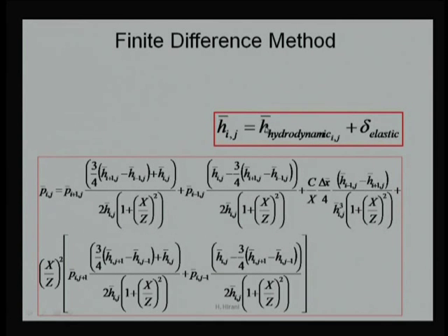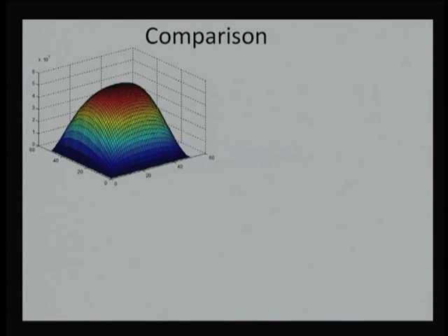So, this will turn out to be more complex and much more time consuming compared to hydrodynamic lubrication, but still there is a point: we can verify this whole formulation keeping elastic deformation as 0. Using this coding, maybe add elastic deformation and make a complete code, and after that put elastic deformation as 0 everywhere. Then we can compare this new formulation, which we have done with the full node without accounting for the half node, with the earlier program which we have done with a half node.